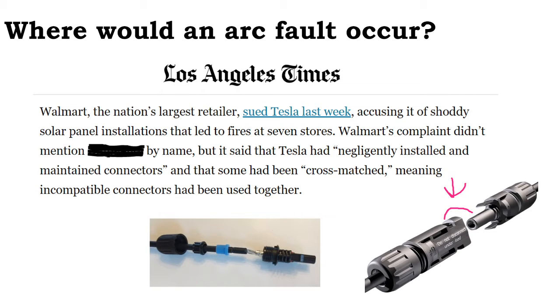That could just be stranded wires on a terminal, arcing across the terminal but still within the circuit, or a solar connector that didn't get fully installed properly, or sometimes the pin inside the MC4 connector. They installed two of the same pin rather than the male and female pin inside the connector. It's a common installation problem.